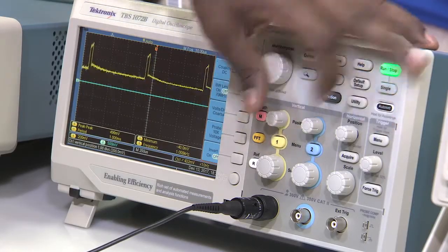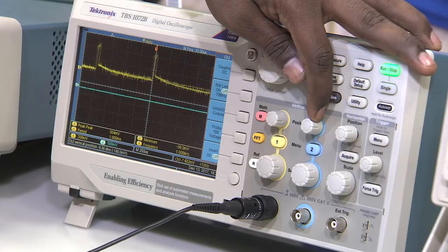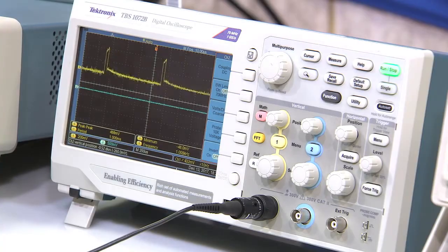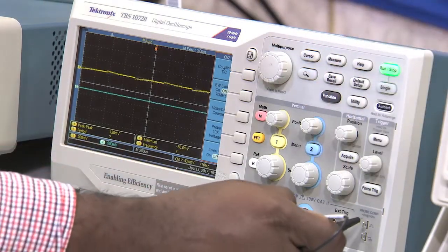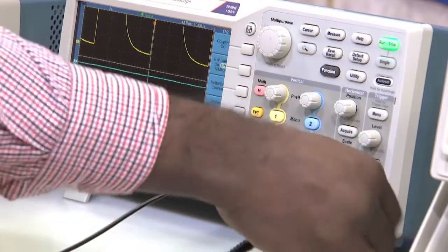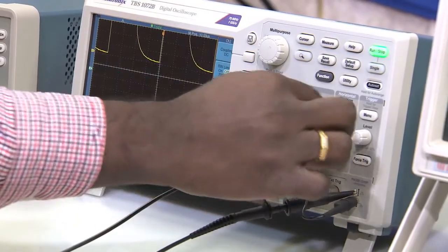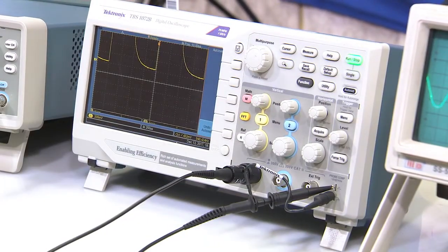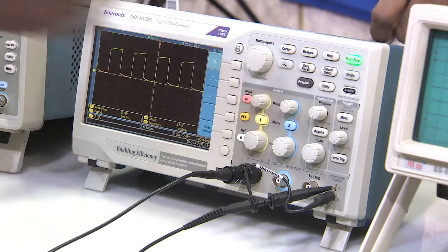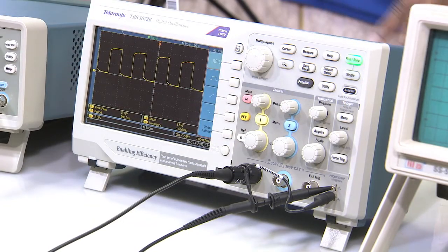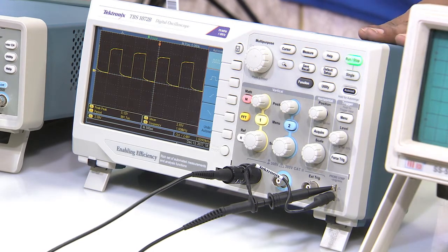So, probably we cannot see it, but to first understand the oscilloscope, you should connect the oscilloscope for the probe compensation. When you start using the oscilloscope, the first thing that you have to do is compensate the probe. That means, you connect the probe to the oscilloscope, to the probe compensation terminal. It is right here, you can see he has connected to the probe compensation terminal, and the other one to the ground, and then he is doing the auto set. The auto set button is there. Can you please show the auto set again? Auto set, right. So, you press this and the probe compensation is done. After you compensate your probe, only then start using your oscilloscope, all right. It is a good practice to always do a probe compensation.